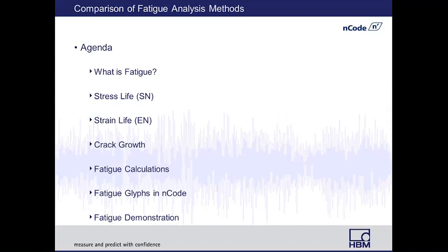So let's go ahead and take a look at the agenda for today. What I'd like to start off with is just answering the question, what is fatigue? So we can get a really good idea of that. And then we're going to jump into the 3 general, commonly accepted methods for doing fatigue calculations. Those are stress life, strain life, and then crack growth. I've got a couple of slides on the inputs required for those different fatigue methods and how we actually do the calculations. And then a slide on all of the glyphs within the nCode application that have to do with fatigue, and then we'll wrap that up with a demonstration.